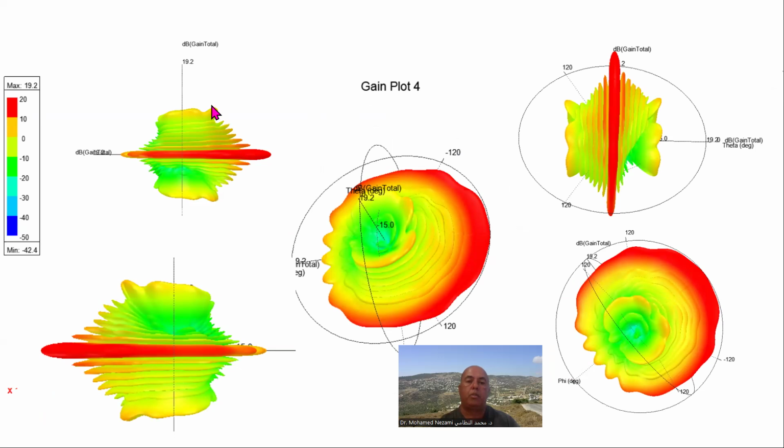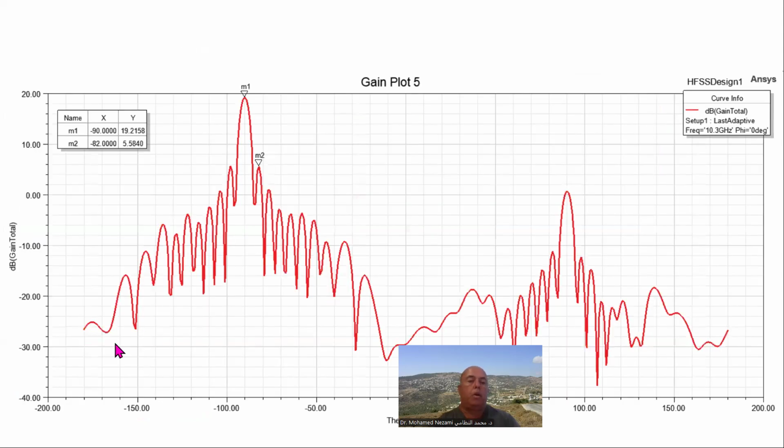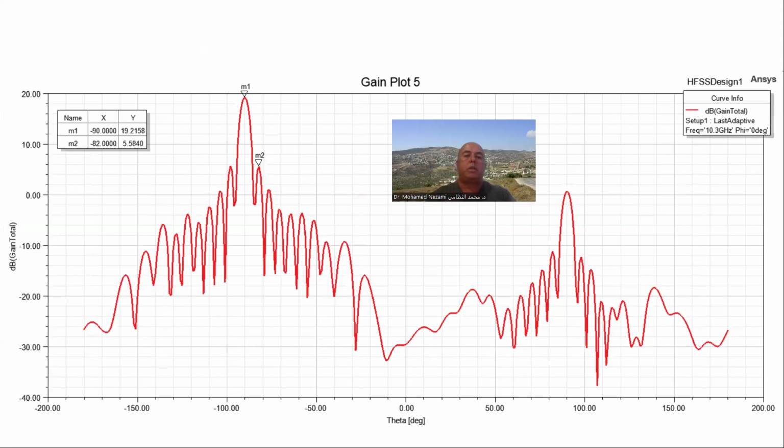Of course, the side lobe level is high in here. This is only 13 dB down. And in the next session, or the session after, we will revisit this same design. We'll do tapering so that we can bring down these side lobes. Now if you look at the minus 180 to plus 180 radiation pattern, you end up with exactly this here.